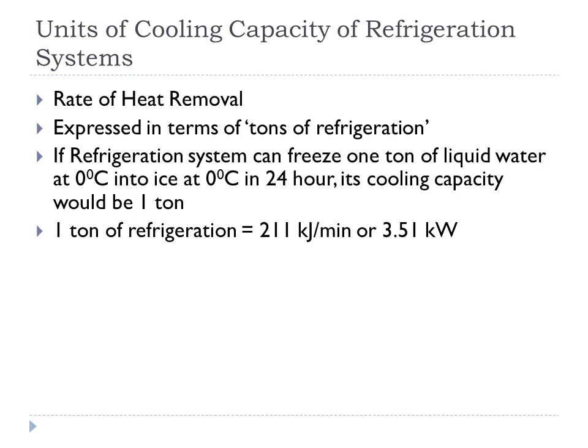Ton of refrigeration is defined as the capacity of a refrigeration system which can freeze 1 ton of liquid water at 0 degree centigrade into ice at 0 degree centigrade in 24 hours.